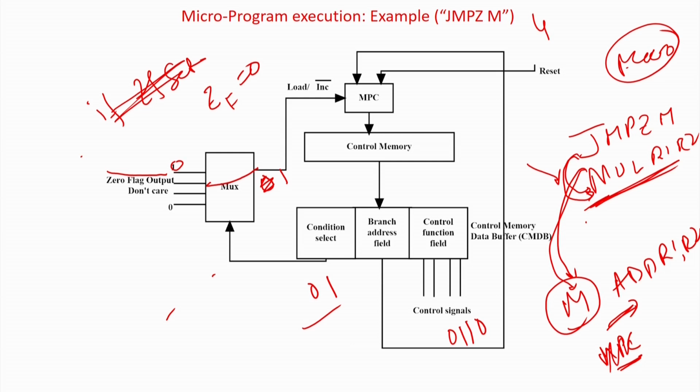We are assuming that the different instruction is placed in memory location number 12, which corresponds to jump on carry. So if this is the case, there will be an implicit jump from memory location 3 to 12, and again it will come back to location number 5, and it will execute 5 and 6, which is common to both. This is an implicit one, and this is there for optimization. But the other one is explicit, it has to be there for the correct operation of this macro instruction jump on M. In that case you use the 0 1 condition which checks the output 0 flag bar.